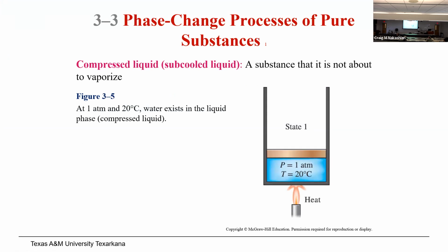So naturally, we have to heat it. This is initially water at atmospheric temperature, room temperature is 20. And basically, this is a sliding boundary. What is the purpose of the sliding boundary? It will not let water vapor escape, and it will keep constant pressure, because you know that whenever we are heating something, it will try to expand. If I am constraining expansion, the pressure will rise. So I want to keep the pressure constant.